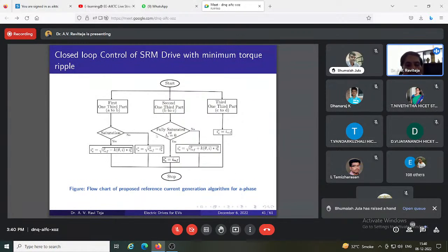And if it enters into the negative slope region, then the negative torque also has to be compensated. So I have to generate more torque here, so the reference will increase further. We ensured that we maintain the square relation because the actual torque on the SRM winding is proportional to I square, not I. If it was I, we would have made it I ref minus I. But since it is I square, we maintain the square relation and keep the torque constant.